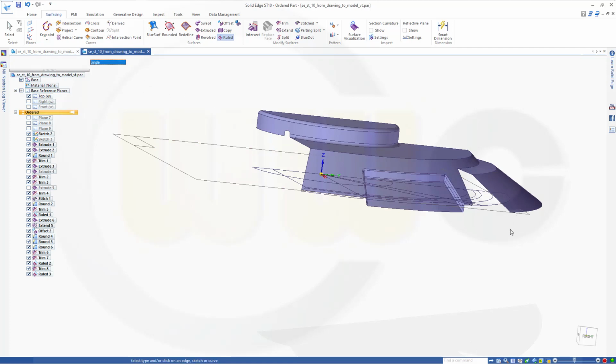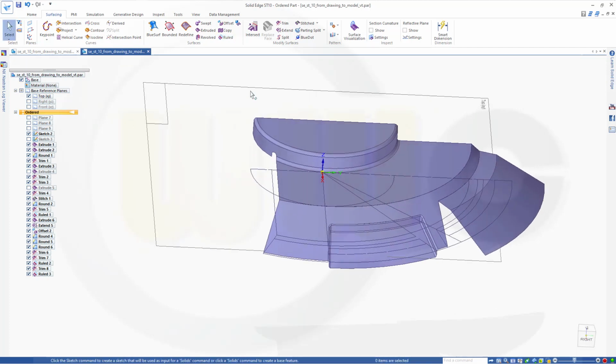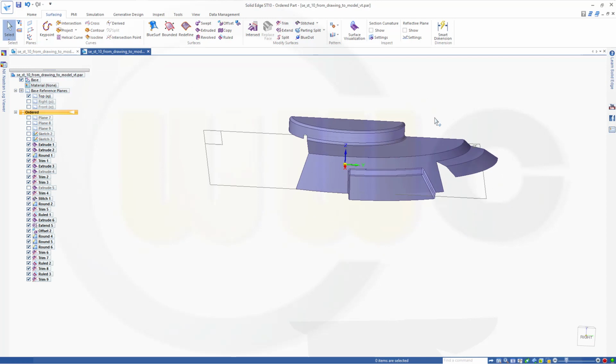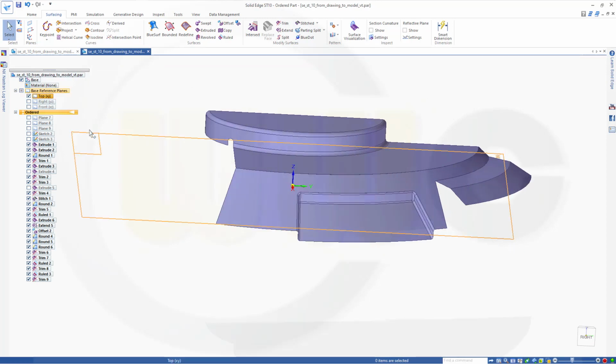and cancel this. Now another trim. I want to trim this surface. Right click with that arc here. Yes. Right click, and I want to remove this side. Confirm, finish, cancel this out. Now let's hide the sketch, and I could hide that plane.